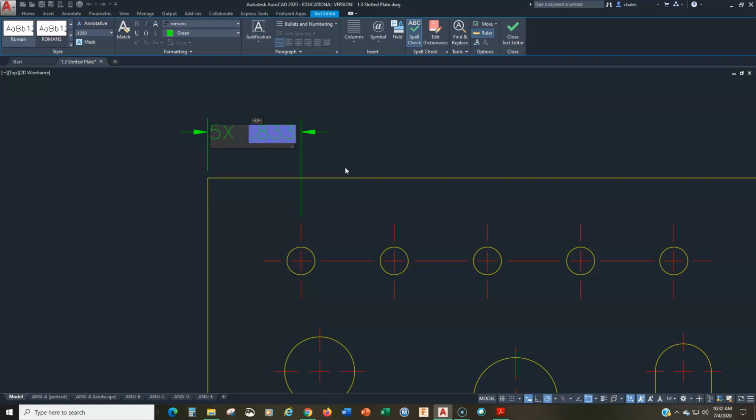Now, if I hit enter at this point, it's going to go to another line. Well, I don't want that. Here you have to understand that normally AutoCAD interprets an enter key press as execute the command, finish the command. Here, because we're in a text editor, enter is like it would be in a text editor, literally start a new line. So if I hit enter, it's going to start a new line right there. So I'm going to use backspace to go back. That's not what I want to do.